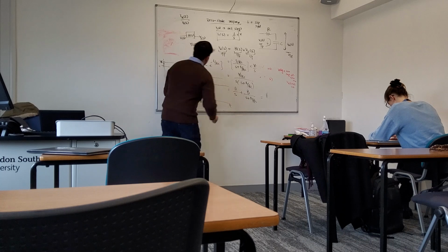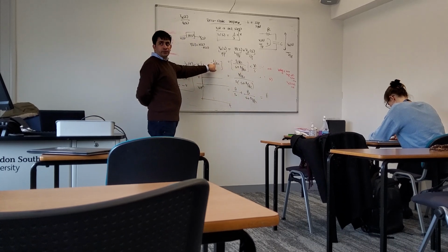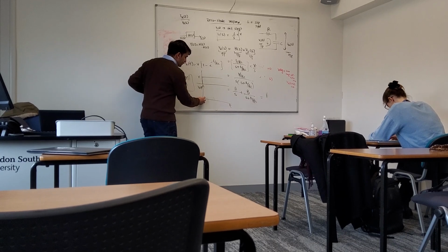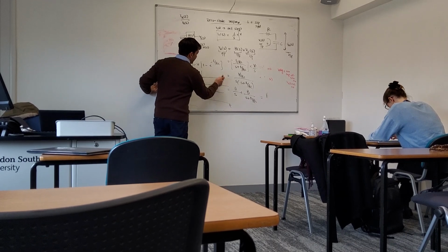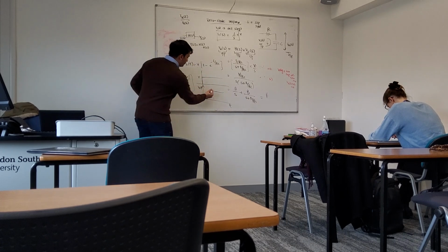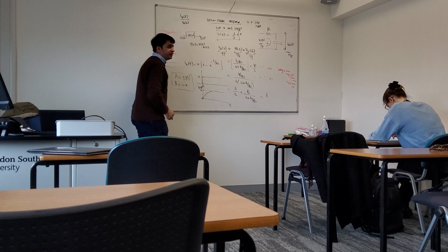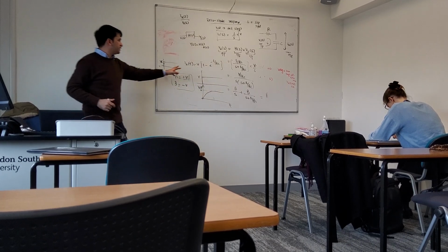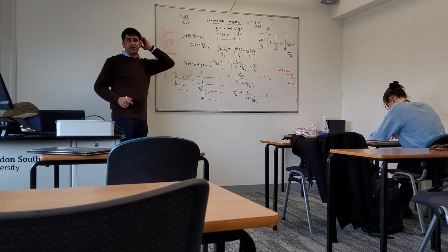So this is time. If I put t equals to 0, e power 0 is 1, 1 minus 1. So it will start from 0, it will slowly rise, and if I put t equals to infinity, e power minus infinity would be 0. So the maximum value that it would reach would be V. So it would start from 0 and go up to V. And this we get from its time domain function.